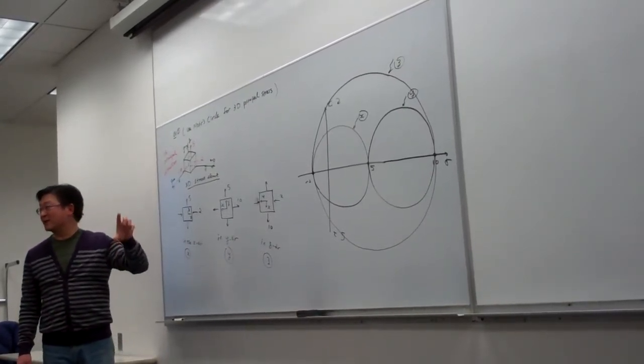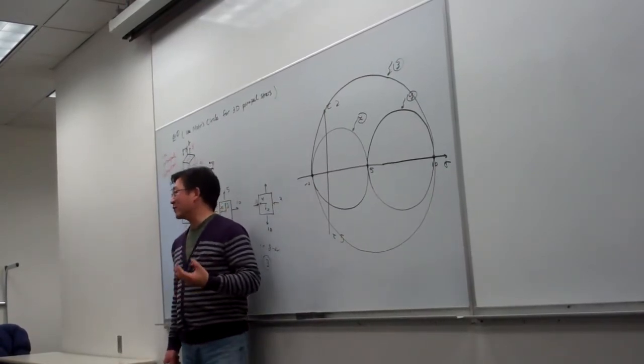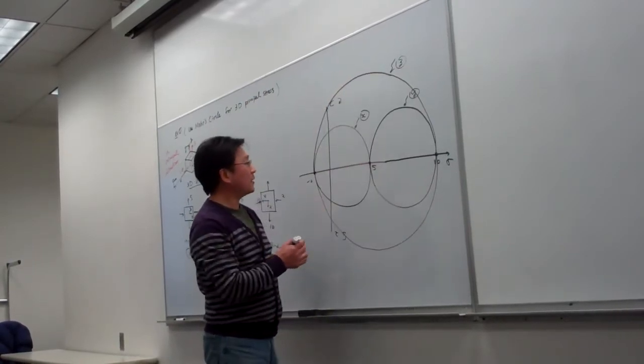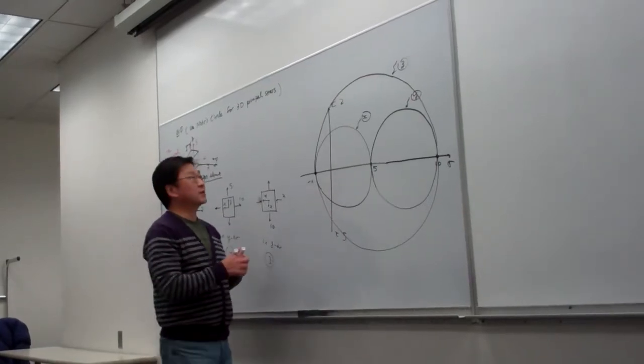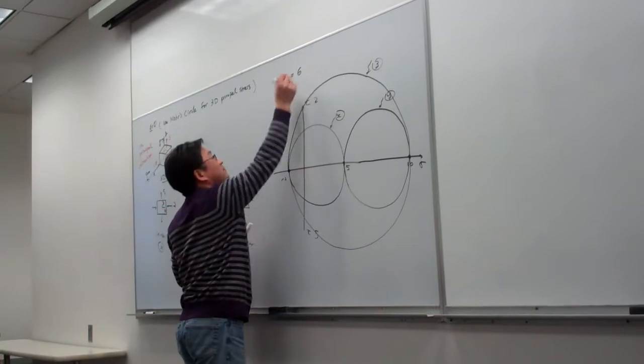What is the maximum shear stress? It is the radius of the circles, right? Right now we have 3 circles, and I'm looking for the biggest one. So that should be this one, the biggest one. The circle has a radius of 6. So for this case, the maximum shear stress will be equal to 6.